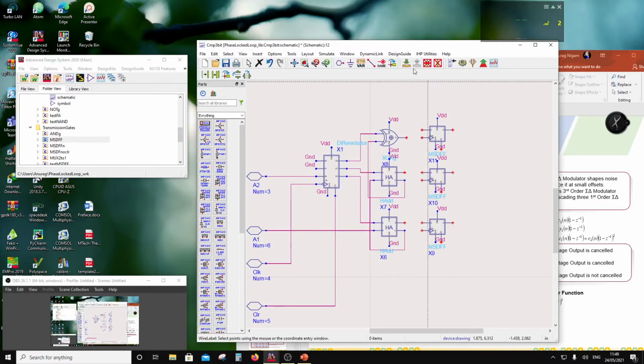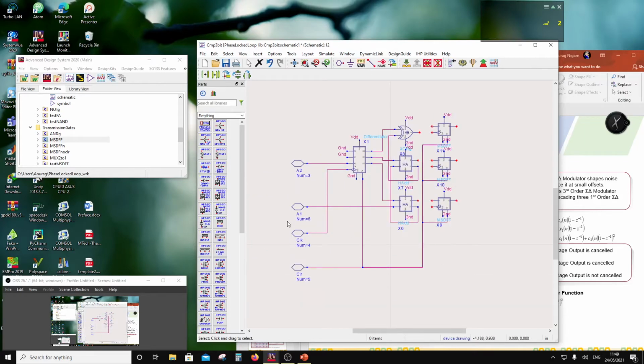So this being done, I need to connect the clear signal. So that's a clear signal for all of them. Correct. And then I'm going to have a clock. So for the clock, I'm just going to introduce 2 delay networks here and then introduce a clock.